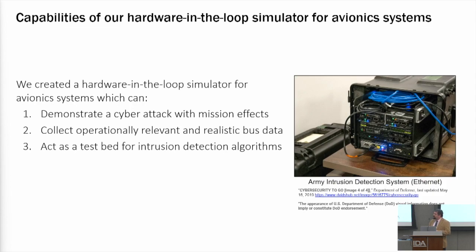They can collect operationally realistic and relevant bus data. So a lot of the literature is done with simulators, with circuit cards that create these messages. One of the main examples, they randomized all the ARINC 429 messages to make sure they sent all the possible labels and messages that one could send, but that's not operationally realistic. It just covers the space.